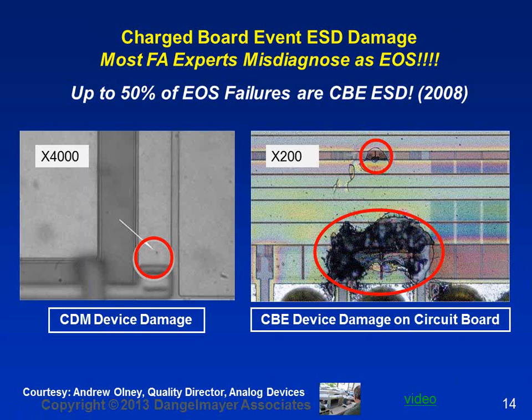So Analog Devices went back through their records and reassessed their determinations of failures and determined that somewhere in the vicinity of 50% of what they previously categorized as electrical overstress failures were actually ESD due to the charge board event. This is an incredible discovery. It takes ESD out of the realm of a significant problem into what many argue to be the #1 assignable cause of electronic device failure.